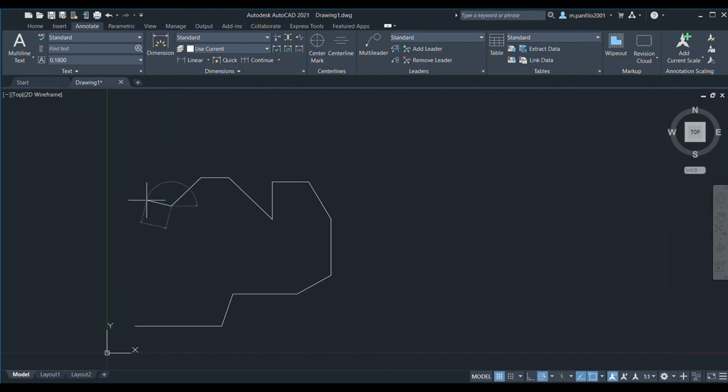And then just move straight to the left side, then type 1.0, enter, and then slightly downward with an angle of 60 degrees. First type 2.3, the length, and then tab, and then type 60 degrees, and then press enter.